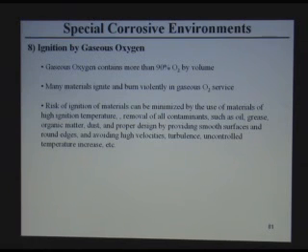So there are ways to avoid that. You have to reduce your velocities. You have to reduce your pressure drops. You have to use materials that are resistant to oxygen burning. You have to remove all contaminants. If you have even dust or oil inside the equipment before using oxygen, these act like a spark, an igniter for oxygen to start the reaction and burn the whole thing. So you have to clean the system of oil, grease, dust, and any organic matter that can cause ignition, and this will promote the ignition of the rest of the equipment.